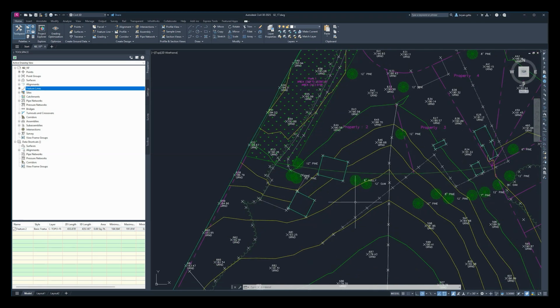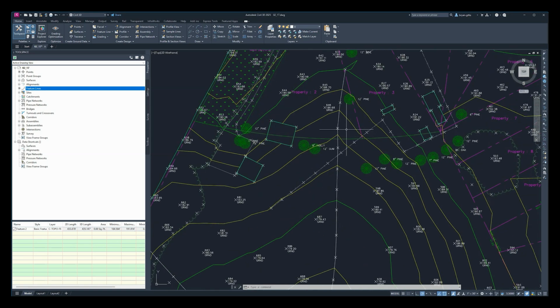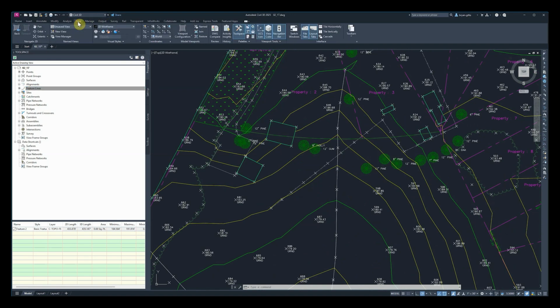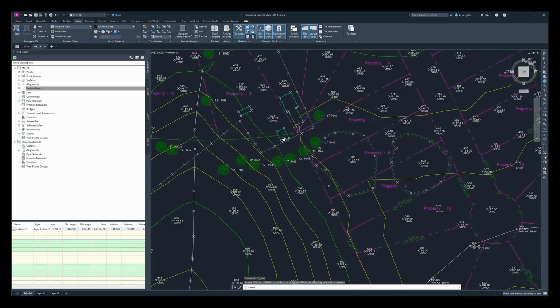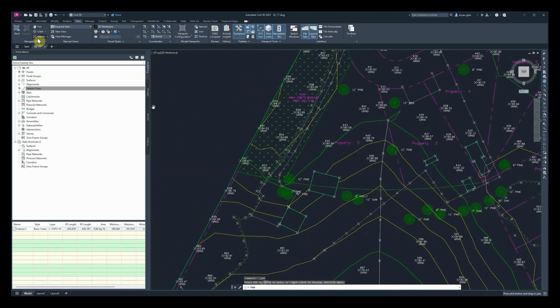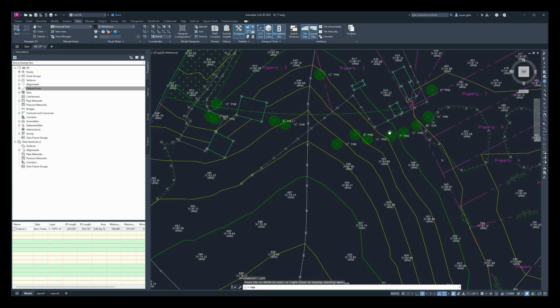Okay, identified it. So instead, I'm using keyboard and mouse commands at times or macro commands to get to it. Instead of hitting the view tab where you could switch to pan view or work with extents or orbit, I'm just using the mouse. So again, it's the escape key I'm hitting to make sure that I'm not in a tool.